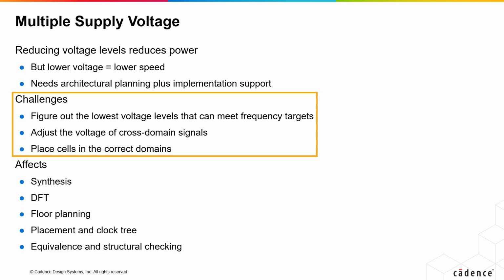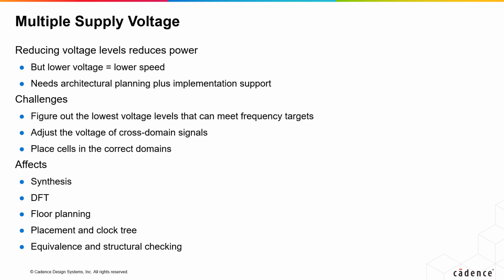So when you are using multiple supply voltage for your design, there are certain challenges that you need to take care of and plan its implementation. Because it affects synthesis, DFT, floor planning, placement and clock tree, even equivalence checking and structural checking.